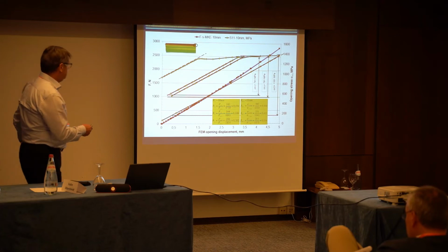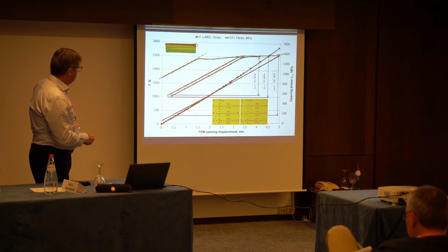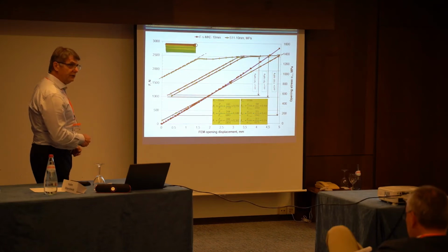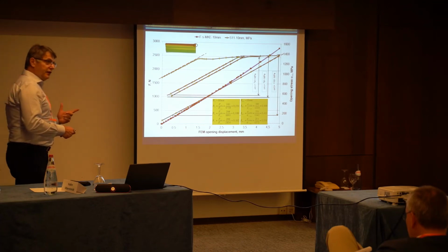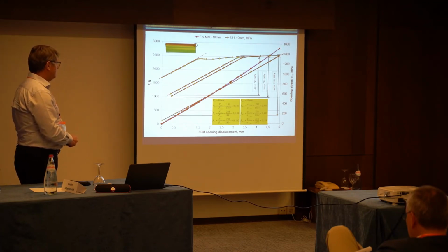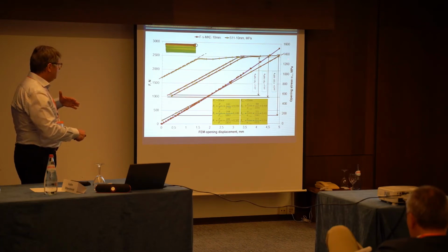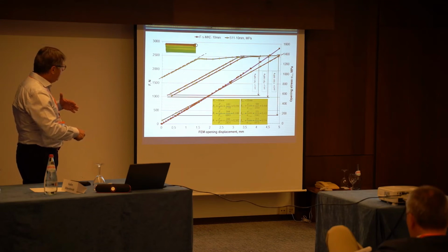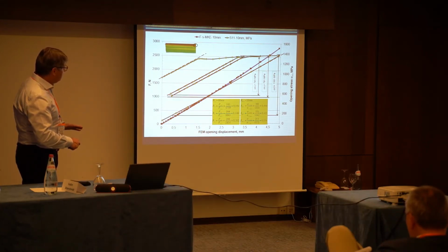And here you can see only one single point, which we consider here. This is in the half of the specimen, it's the H. The second half is here. So this point is critical. We proved that in the middle we have crack initiation, and our residual stress when we start with fatigue is here, in megapascals. This side which we have here belongs to this curve, but we start to load. We start from zero to load, and we go along this loading curve.